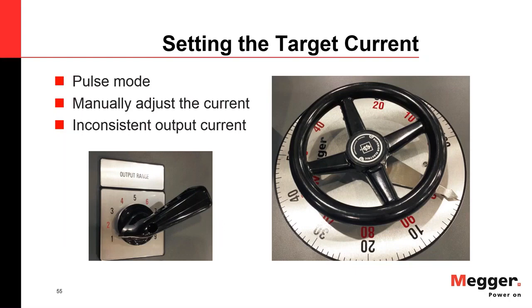A challenge is always adjusting the currents, and all of the classic testers, before we come to the last topic, the advances, all of the classic testers, doesn't matter from what manufacturer, they have a variac and they have a transformer. That variac is feeding into the transformer, and you have 2 different means of adjusting. You have a coarse adjustment, what you see on the left, different stages, a coarse select, and then you have a variac on the right that gives you the fine adjustment within a stage.